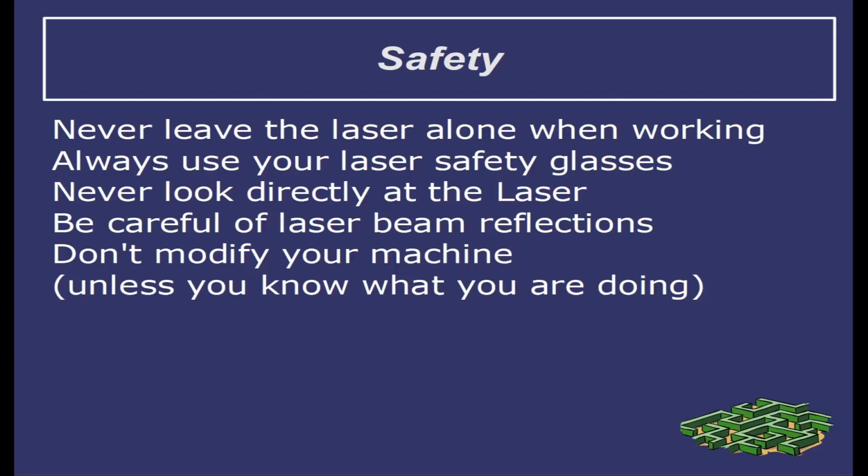Never look directly into the laser. Be careful of the reflections that you get. It's amazing how you can get reflections from a laser all over the place. Don't modify your machine unless you know what you're doing. But I would say never, ever modify it.